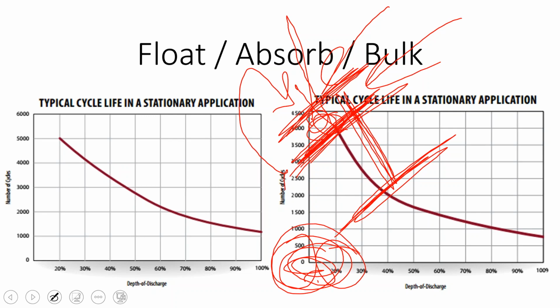And we haven't talked about it yet, probably get into it tomorrow, but the way that batteries degrade, you can prevent the battery from degrading by charging it up all the way to the top of the float every so often. It's just not energy efficient to do so. So you don't do it on a regular basis.